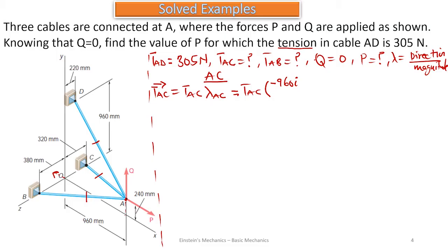Even from this point it is showing us that before you can even get to the x-axis, you have to move down by a dimension 250. And this movement is on the y-axis. Before you get to C, first you have to come down to the x-axis, which is the y movement, and that is also against the direction of y, so it is a negative movement, negative 240 j. Once you get here, you move also a distance 320, also against the original axis, and that is going to be negative